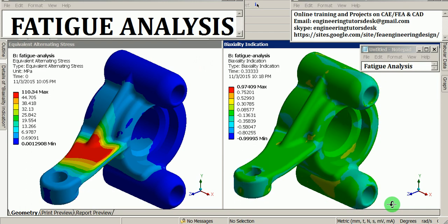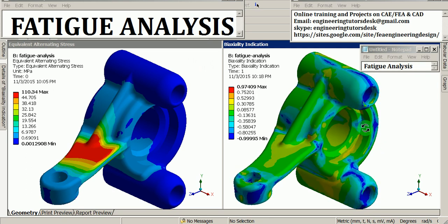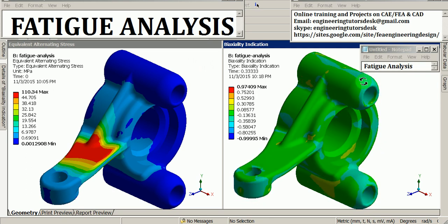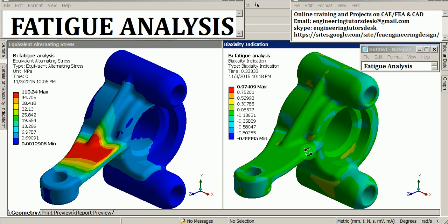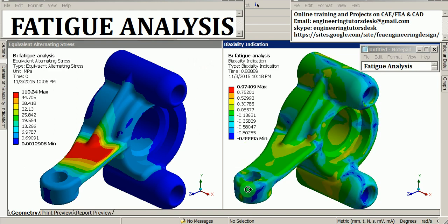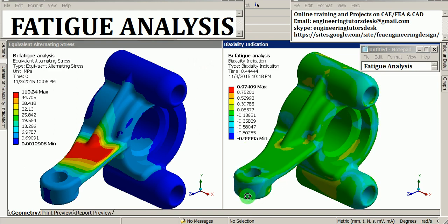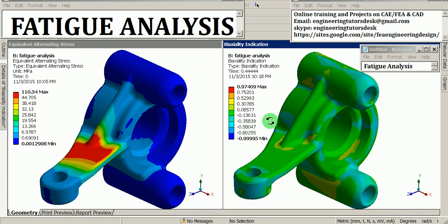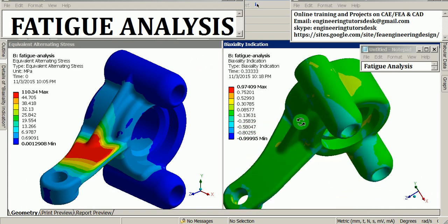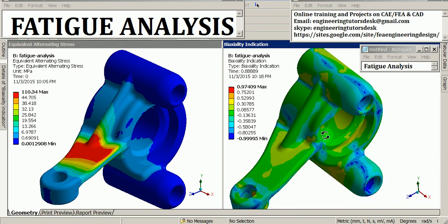Here, the body is made up of structural steel, and has two bolting locations at the top as well as the bottom. An extended lateral arm is experiencing a force of magnitude 200 newtons, which is a cyclic loading or fatigue loading. The member is supported by a supporting rib to add strength.